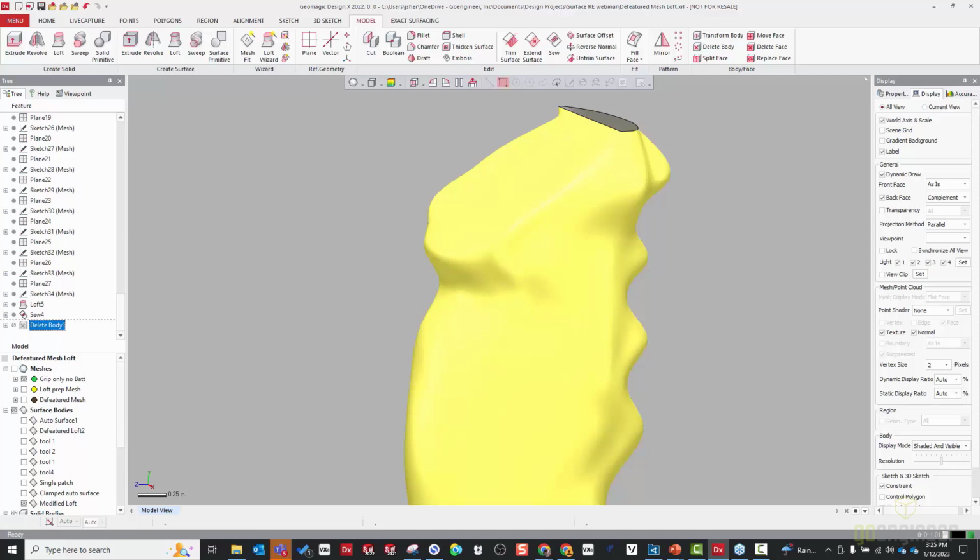So Drew said that for lofting, his experience has been that guide curves are extremely important for good results, but their location at which they intersect each sketch is also key. Yeah. So in many programs, guide curves, in order to be used, they have to have not just a point where they intersect each cross section, but they have to have a specific relationship in the sketch that clearly defines that there's a Pierce relationship.